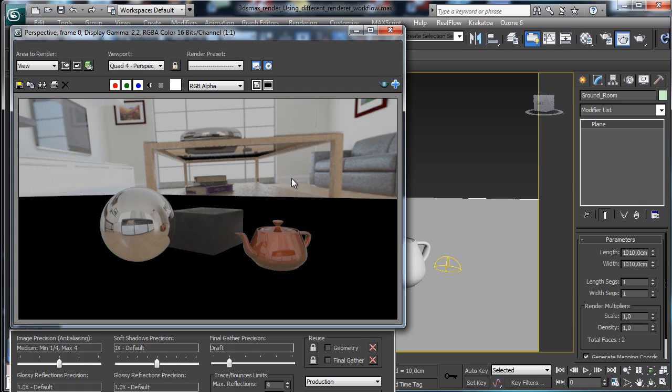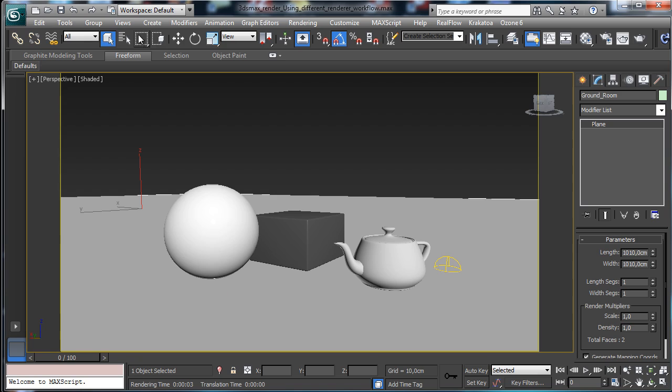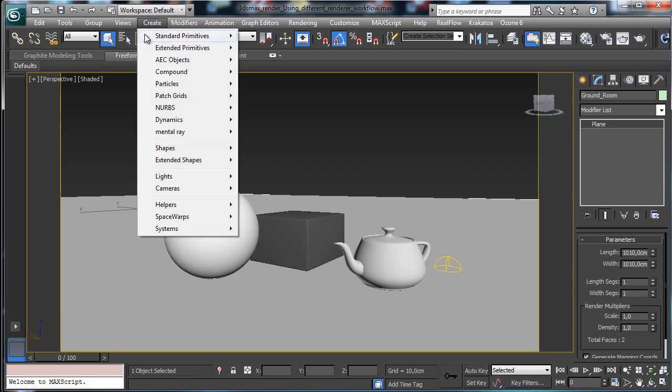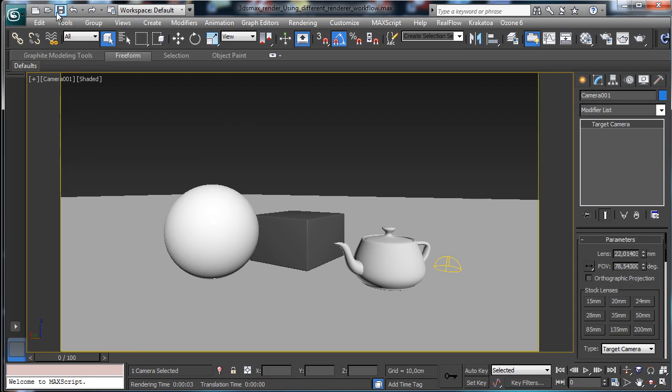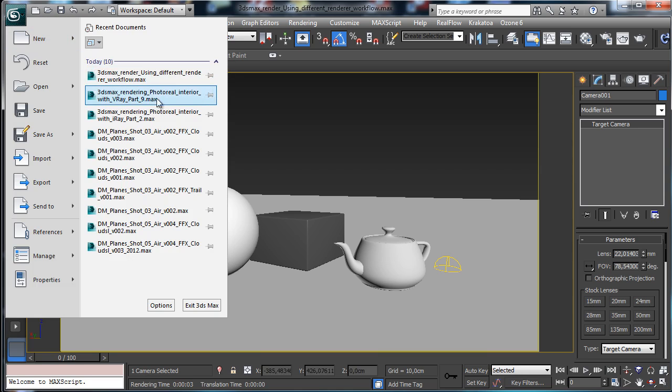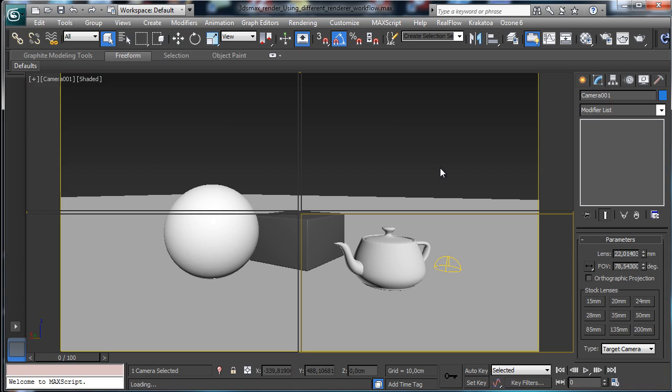A problem that can happen is to have no occlusion there, you see, but you can render a separate pass with occlusion. So in this case we need obviously to render also from this point of view to be sure that we are rendering from the right point of view. So let's save this one and let's create a camera from this point of view. So view, create camera, and save again. Then I go to create a render from this point of view on the other project, just to be sure we can make a test comp.